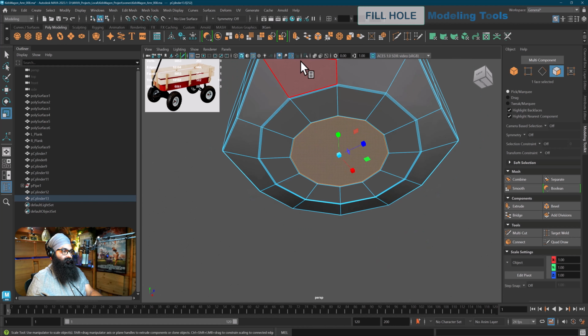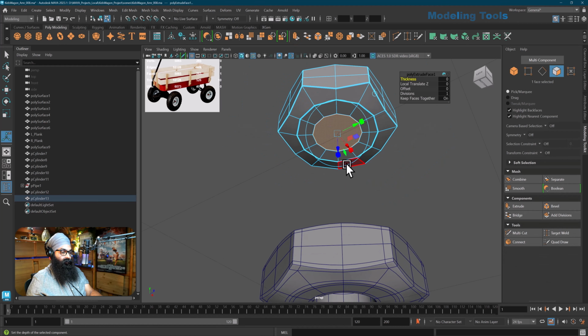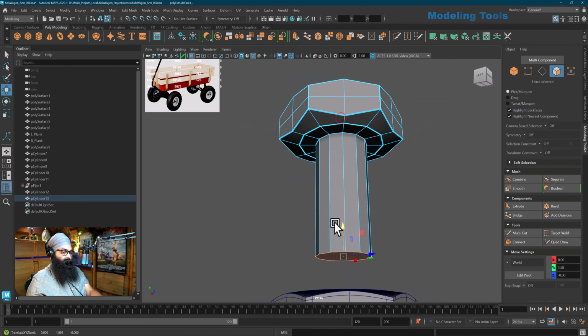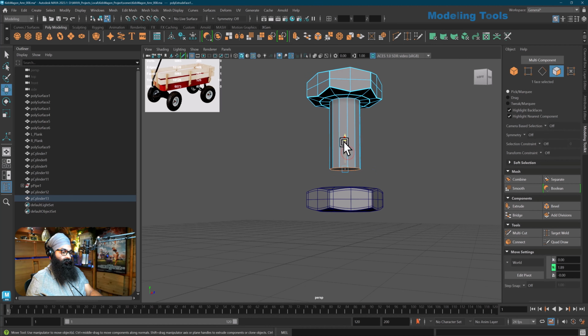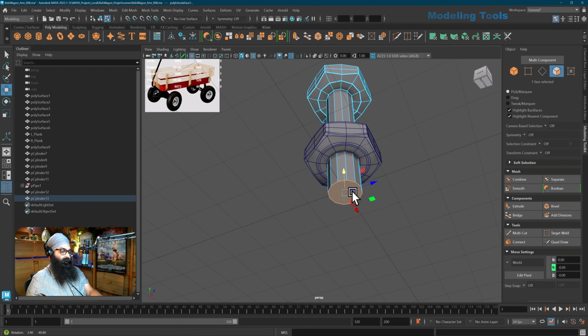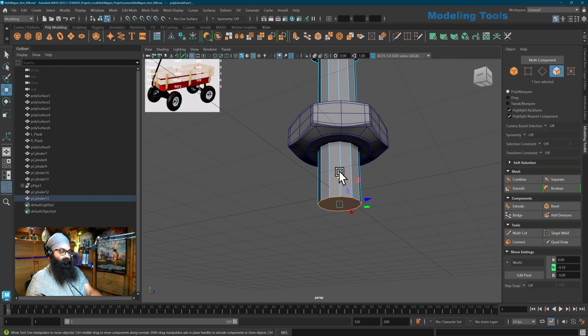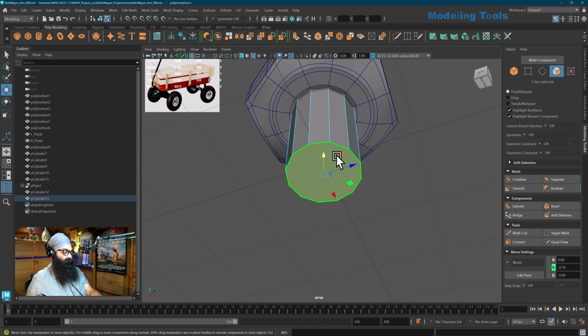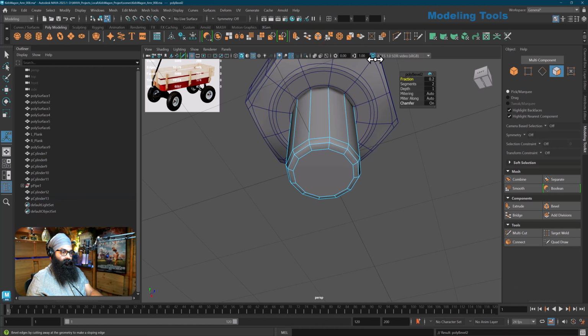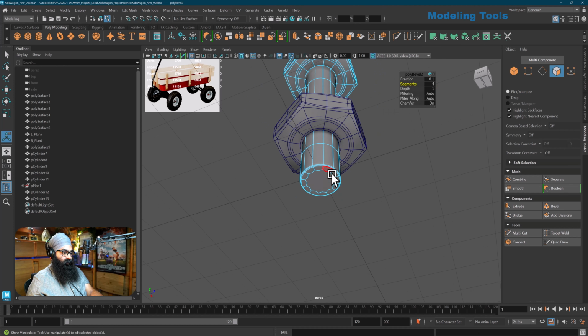So I'm going to grab this and extrude this area out straight down, and let this area go through it and right here, and that's pretty good. Now in the last one I wanted to bevel, because if I hit 3 it's going to go into the shape. So let's double these edges by clicking on bevel and probably set to really low fraction value and set the segments to a little bit higher. And now see, when I hit 3, those edges stay.